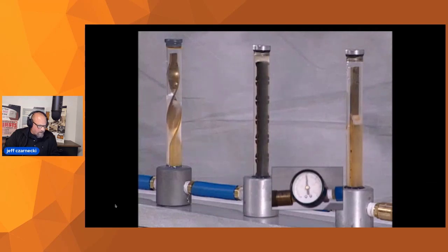Now this video here, it's a bit older. This is available at dme.net, but it gives you some examples where if things aren't installed correctly in a spiral or flat brass baffle, you can get under pressure, you can get the water to blow by or air to blow by, not allowing the water to actually reach the part of the geometry that needs to be cooled. The plastic baffle there in the center is showing you a consistent turbulent flow through the cooling process. In addition, the way that these are made, we have some fins on the side, so they can be installed slightly undersized to avoid blow-by.